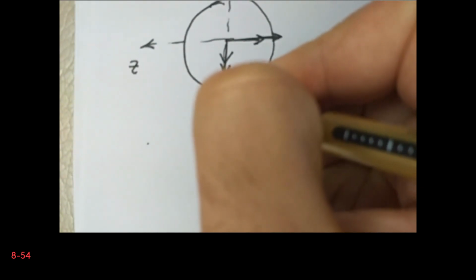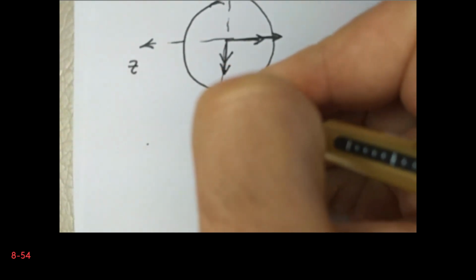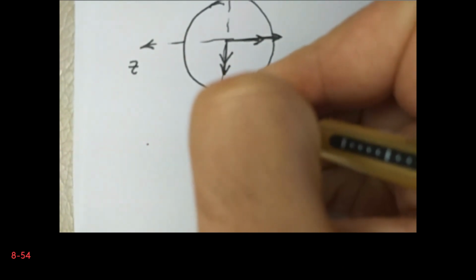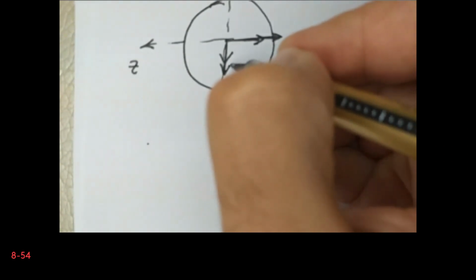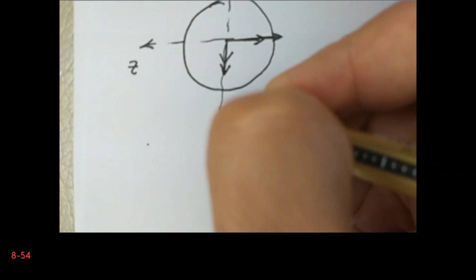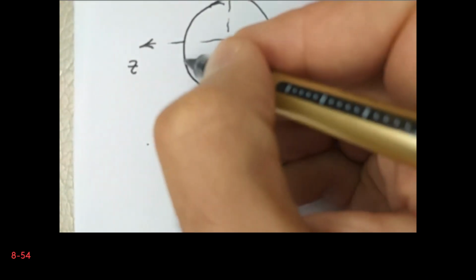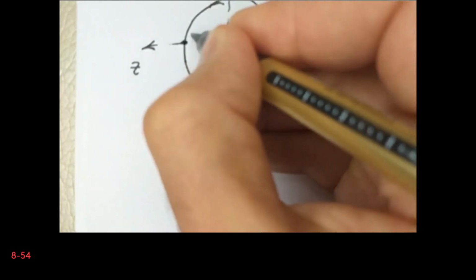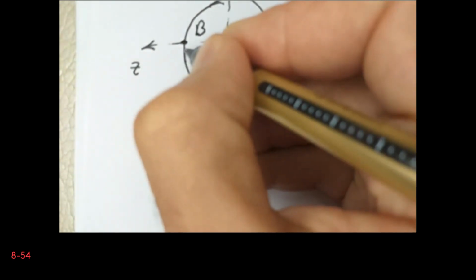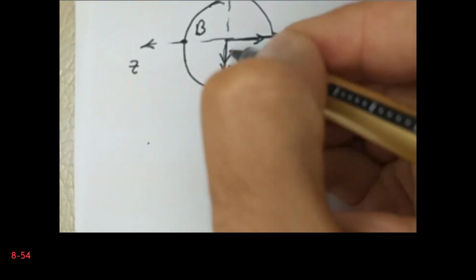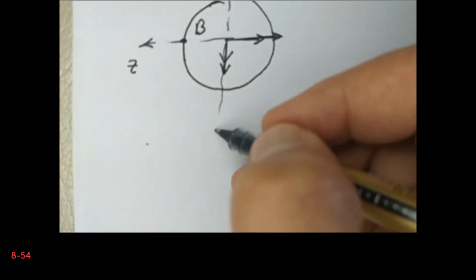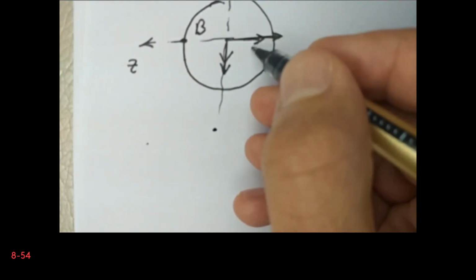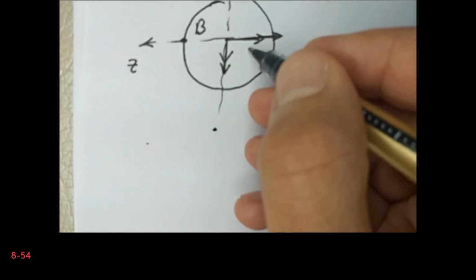So both are, sorry, this is around z-axis, yes, this is Mz, and this is My. Now of course, when you have a moment like this, at point B, this will generate a compressive force because of the direction, and Mz will not generate any stress at this point.